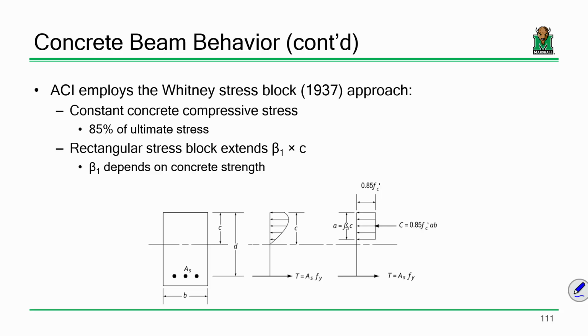So let's look at this beam here for a second. Okay? So I've got a reinforced concrete beam. It's rectangular in nature, and I have an area of steel at the bottom. I make some assumptions. I start off assuming that the steel yields. So if I want to calculate the force in that steel, the force in that steel is the area of that steel times Fy, right? Stress equals force divided by the area. So if I just determine what my limiting stress is, I can determine the force in that steel pretty easily.